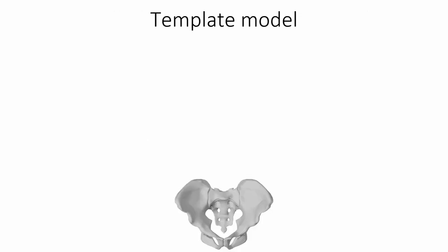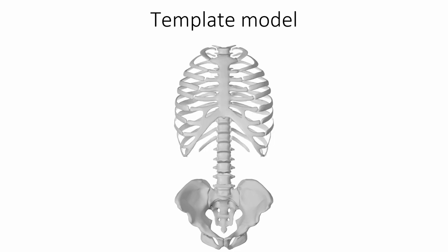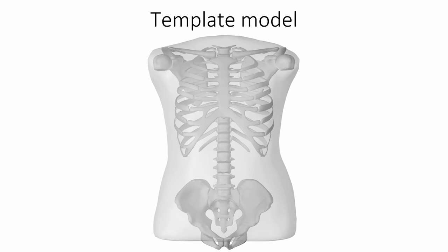The differentiable biomechanics model is initialized from a template. The model consists of the pelvis, the lumbar spine, the thoracic spine, the rib cage, the costal cartilages with the sternum, the bones in the shoulder joint, and the soft tissue. The bones provide the skeletal part of the model, and they are articulated between them, creating a multi-body dynamic system. The soft tissue is coupled with the rigid bodies and simulated with FEM. We chose to include these parts of the body in the model as they are the ones that participate in the transmission of forces from the brace to the spine.